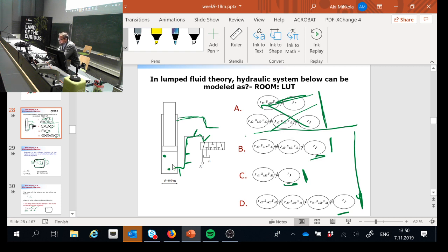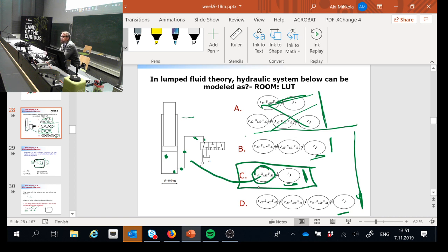And we concluded that we can assume that the pressure here, let me change the color again. Or not. Okay, let's not change the color. But let's explain that the pressure here can be assumed to be the same as here, here, here, here, and here. So it gives us one volume that is needed. Simply, it's only that you need. You just need to have this one. So one differential equation that is associated with this volume is enough to solve the response of this simple hydraulic circuit. One differential equation only.